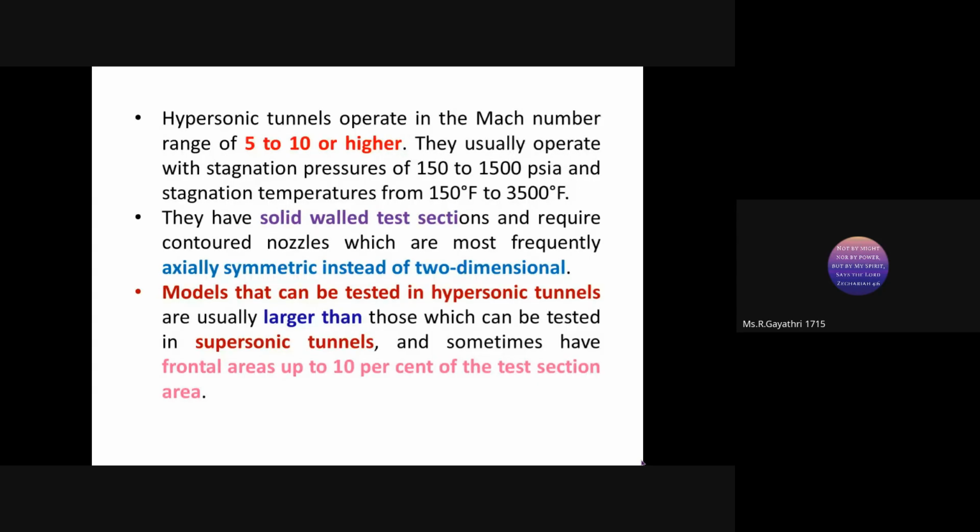In our aerodynamics lab, we changed 3D wing into 2D by ignoring the flow in one direction because we noted little changes in that direction. But in hypersonic case, we can see significant changes in all directions. So we can use 3D nozzle or axially symmetric nozzle instead of 2D nozzle.